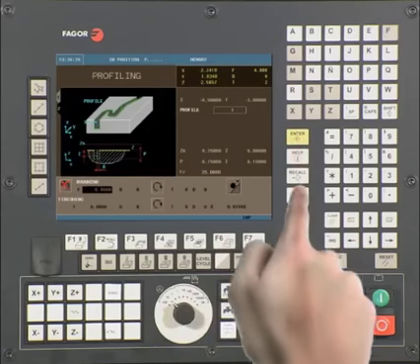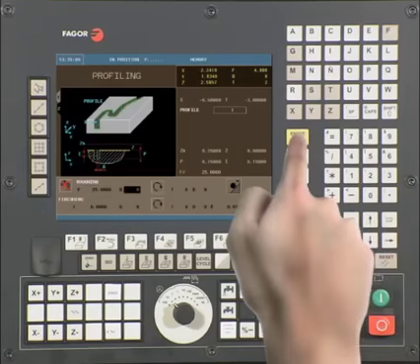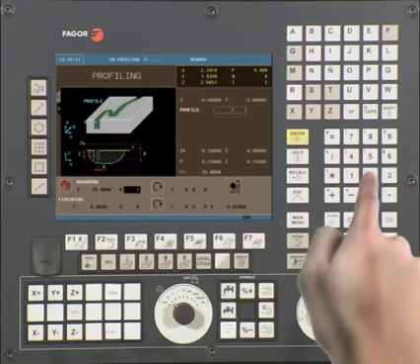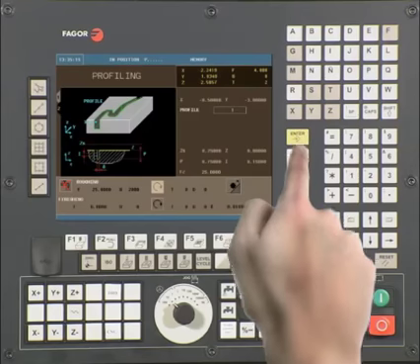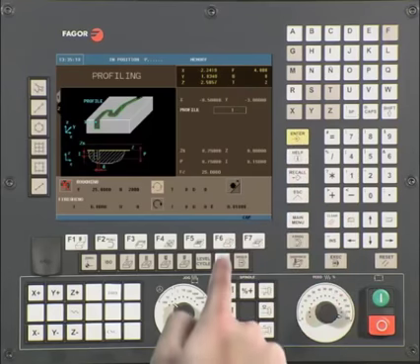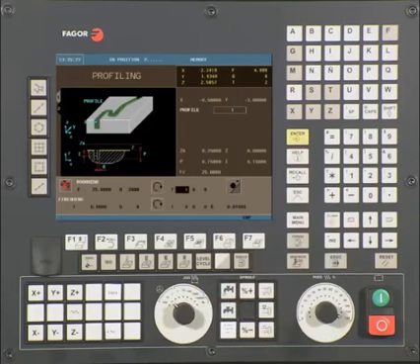F. This is your roughing feed rate along the axis. In this example, we are using a value of 25 inches per minute. S. This is your spindle speed. In this example, we are using a value of 2800 RPMs. Use the half key to select if you want spindle to turn clockwise or counterclockwise. In this example, we will select clockwise.